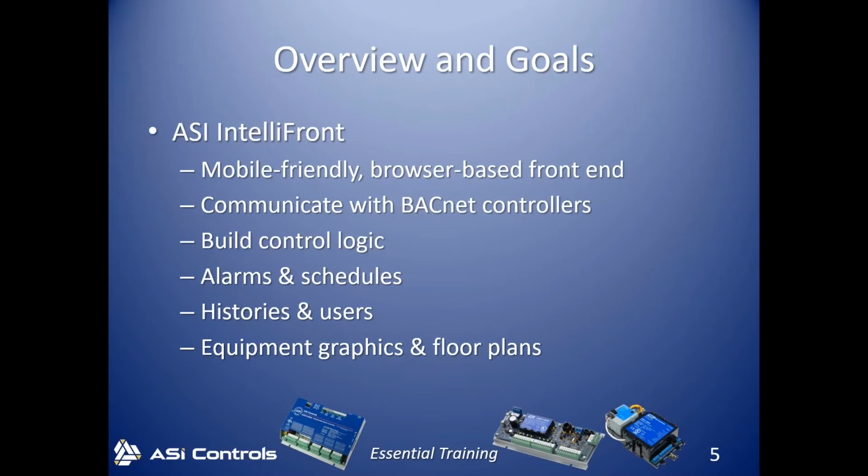It's got a programming interface that you run at the top level outside of the controllers that you can use to do some programming. We'll create some alarms and schedules. We'll do some trends and user configurations. You can limit users to only have certain privileges if needed. And then we'll build some graphics, floor plans, so that you can jump around and see what's going on in your controllers.